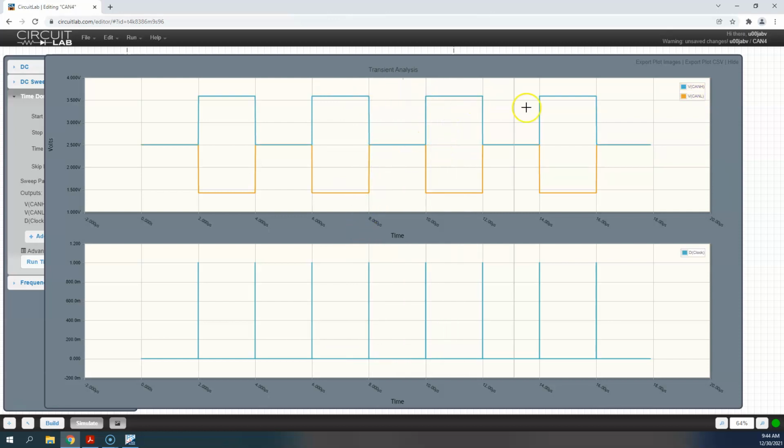If it's putting this message on the bus, then we have to wait until the radio is finished with that message. It's only a few microseconds, so looking at it in time, it's not very long. This is one of the great things about CAN. You can't come onto the bus and say, I've got a message that's more important than yours and you need to stop transmitting, unless the devices start at the same exact period of time, as we'll talk about in arbitration.